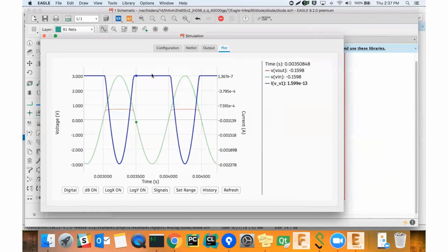So what you can see is that although it's inverted, the value at the top here is pretty close to 0. And as we go down on this dark blue plot, you see the magnitude of the current increasing. I'll explain the sign in a minute. It's going up to about 2.2 milliamps. These are based on the values in the circuit given to the resistor and the voltages seen at the input. So that's what we would expect.